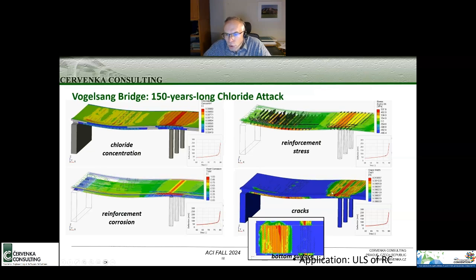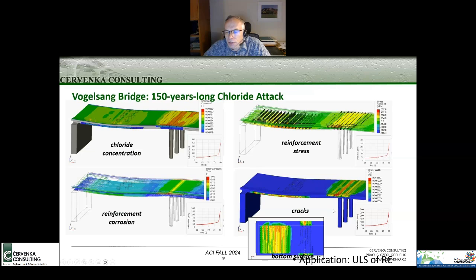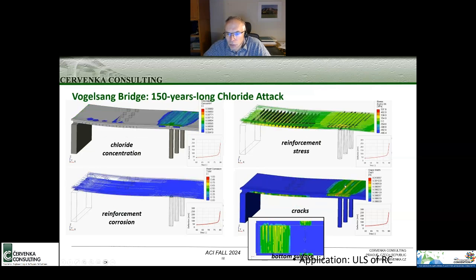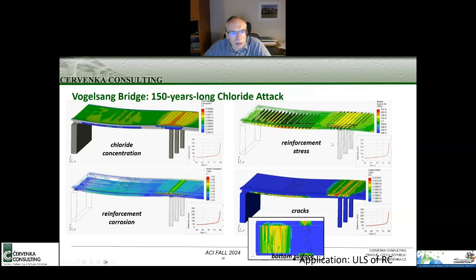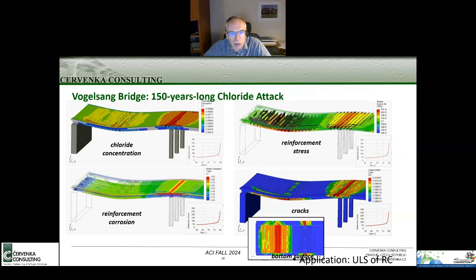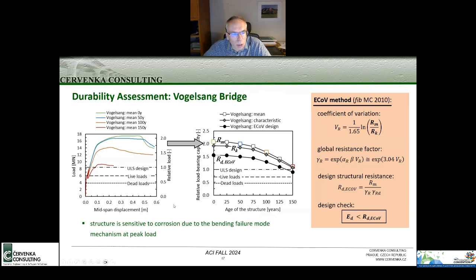And that's why we can also show the cracks not only as lines, but also as their most probable maximum thickness. So we see them in these colors at the top of the bridge and also at the bottom of the bridge. So this somehow highlights some of the unique features of ATENA software for modeling durability problems, corrosion-induced damage, and how we can use that information. So we can use it to calculate the strength of the structure.